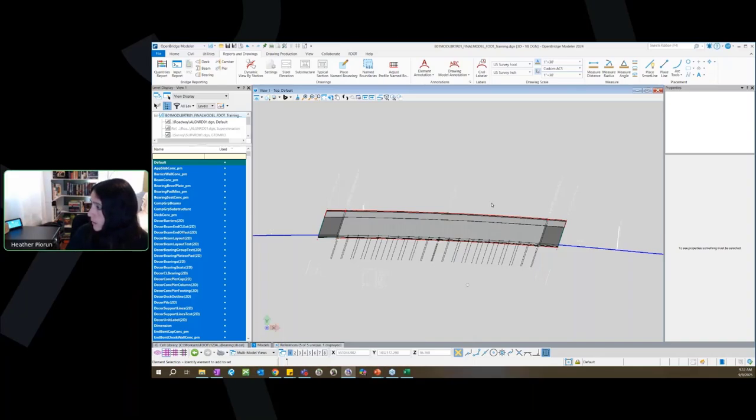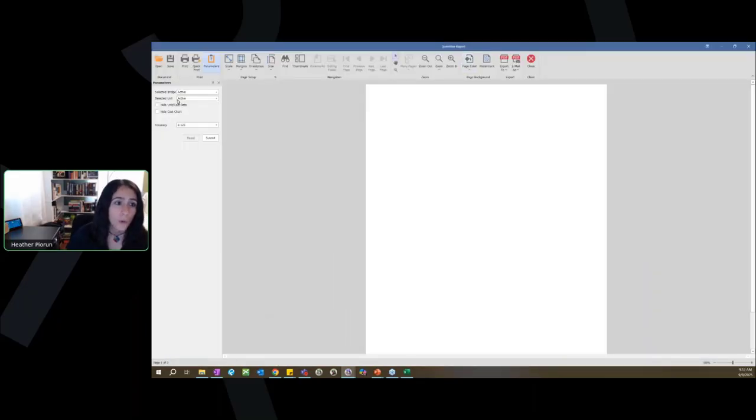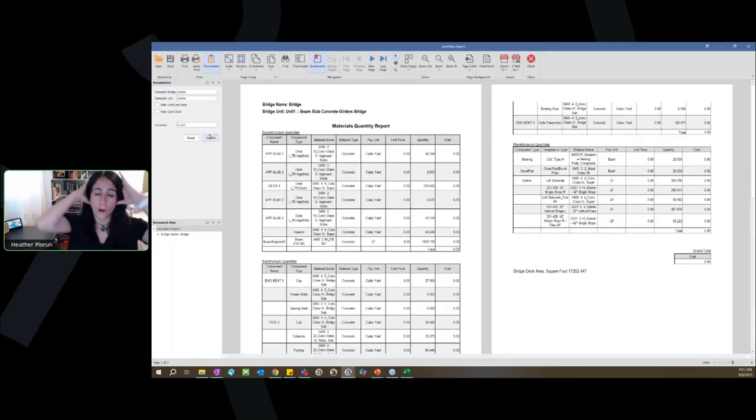I think that I covered... Oh, the OBM quantities report. Let me just touch on that one real quick. For the OBM quantity report, you can have it include cost data if you would like, but I will say in the FDOT workspace, we've gone in and zeroed out the cost of all of the materials. That is because we want the starting point to be zero if people want to go in and assign those unit prices based on either the BDR cost estimating chapter, or if they're using historical costs or whatever. We want people to be able to enter that on their own.